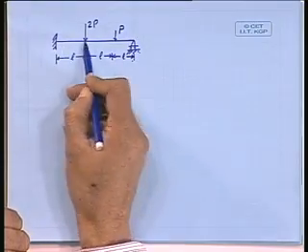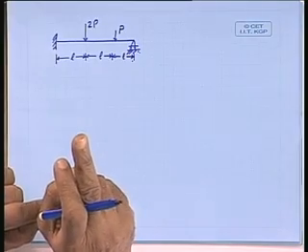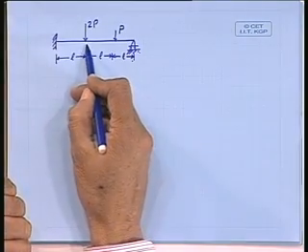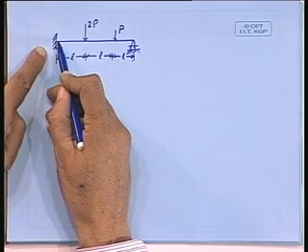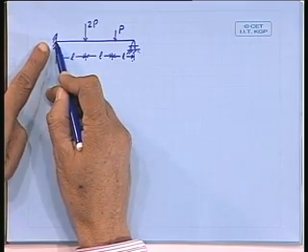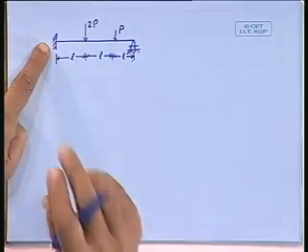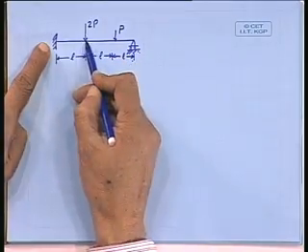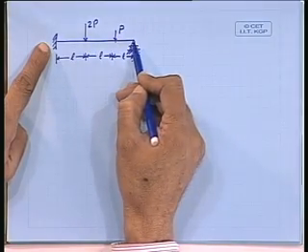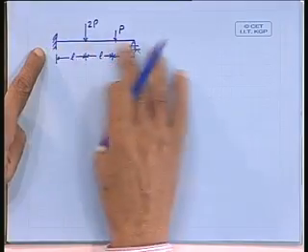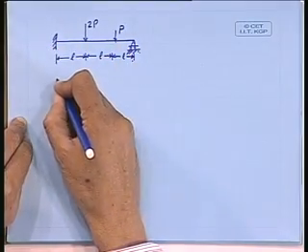We also know that under the load the maximum bending moment can occur. So this is a physical support where the fixed end moment will be there, so this can turn to be a hinge. Under the load excessive bending moment will be there, so this can also turn to be a hinge. This can also turn to be a hinge. This is a physical hinge. Now we have got this combination here, and let us see what combinations we can have.